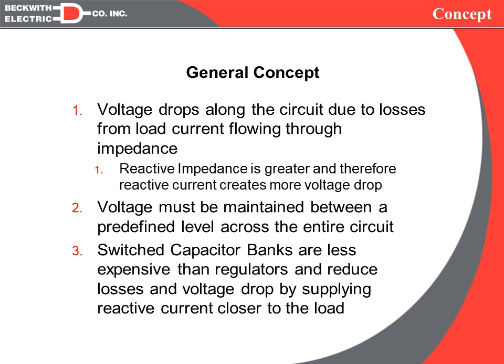And we realize that we have to maintain the voltage between predefined levels. So we have a low level and a high level, and every customer across that entire circuit must be within those levels. And if we can run the voltage at a lower level, we will reduce the load current and therefore reduce the losses and the voltage drop also.